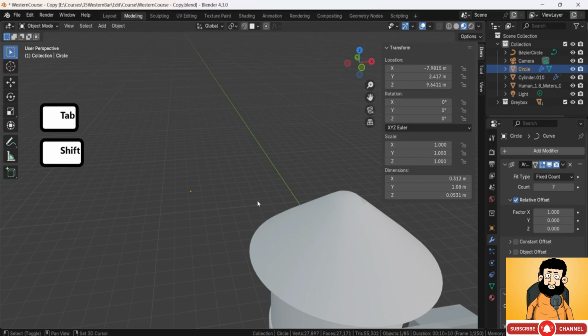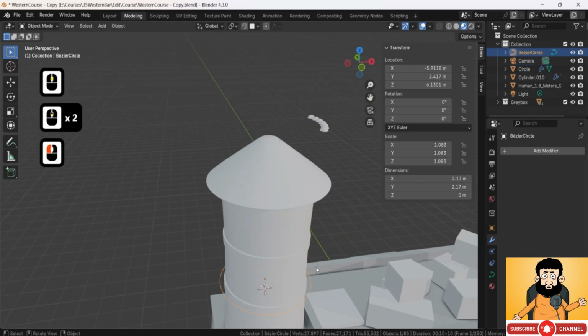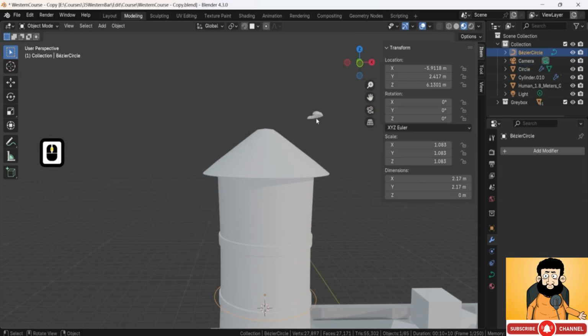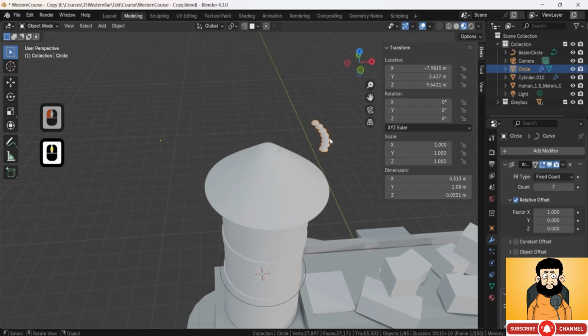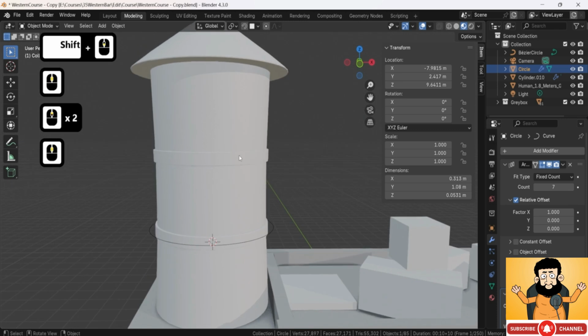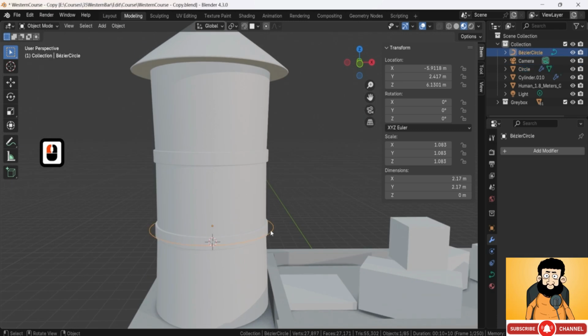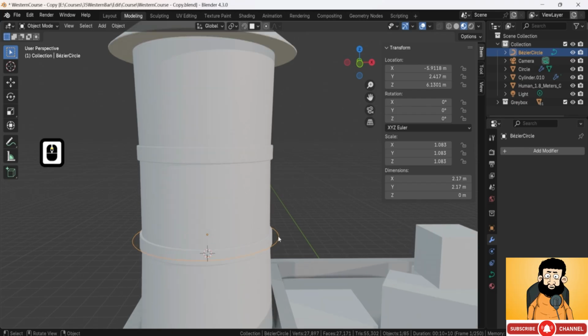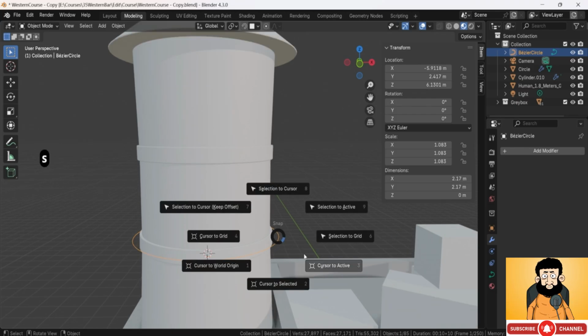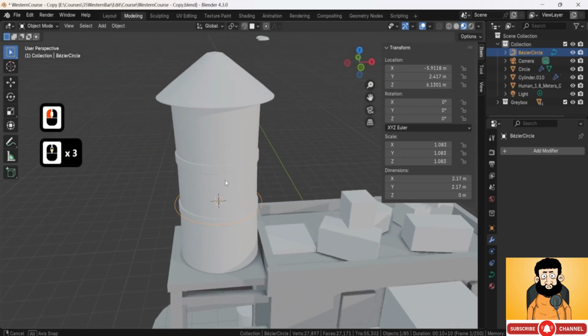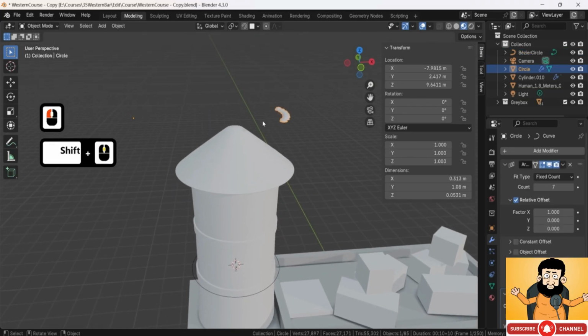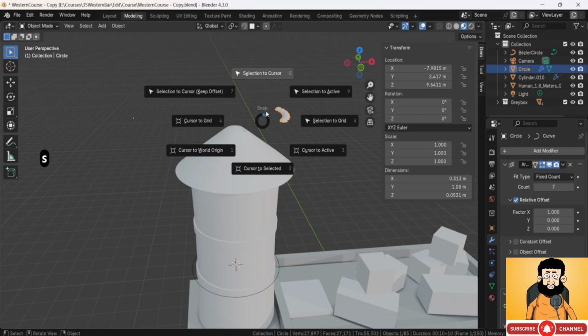All right, so the next thing is going to be going back. We need to put this origin point to be aligned with the bolts that we have over here. So for us to do that, just in case, we're going to go ahead and reset the curve setup with the 3D cursor. We're going to select the curve, press Shift+S, and choose Cursor to Active, there we go. And then we're going to select the bolt, press Shift+S, and do Selection to Cursor.